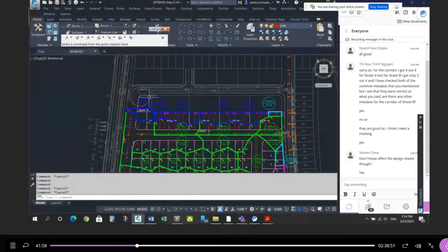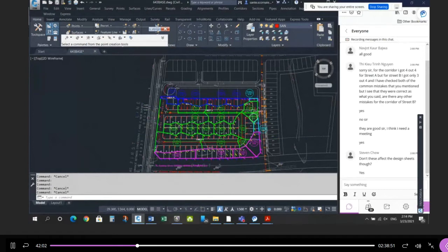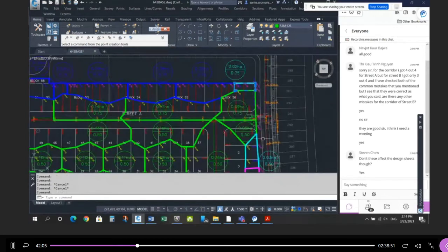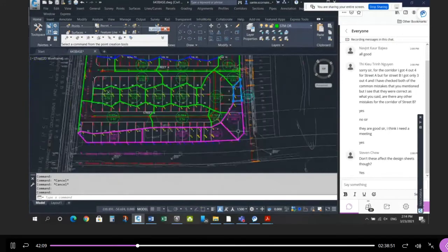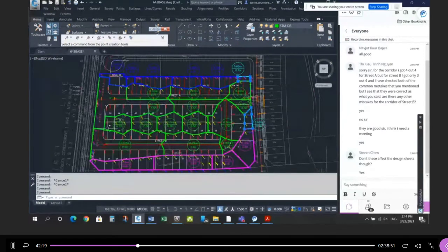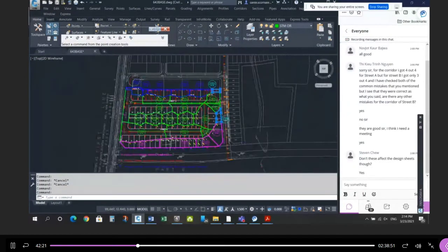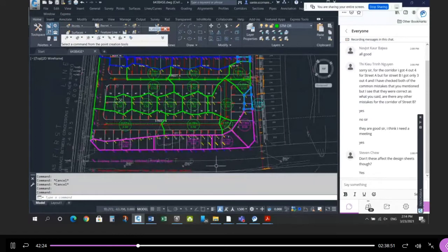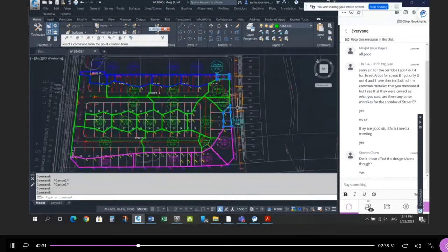So those blue areas, those dark blue areas, are all draining to the north. Everything that's green is draining through the site. This thing here and this thing here is draining to this existing pipe system. And then we're also going to look at whether these backyards are allowed to flow into this road and into the pond here. So we'll look at that. So potentially we're only designing for the blue, the internal green stuff. I'm going to assume that these are allowed to flow out here, and then we'll check it and see if it's true or not. All right, any questions so far?